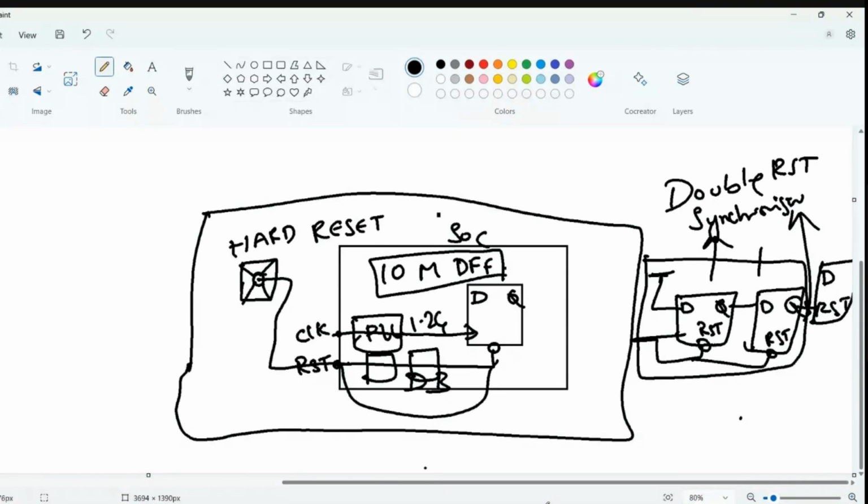Yes, sir. So do we use reset only for synchronous, or for asynchronous also? In general, in all the internal circuits, we always use a synchronous reset. For DFT, we prefer using asynchronous reset. Again, that is a different case. Synchronous reset is not controllable, in the sense you need to add a cut point here for DFT. Again, we will not go into the DFT concept. In general, we are currently going through digital electronics, so we are in the RTL perception.